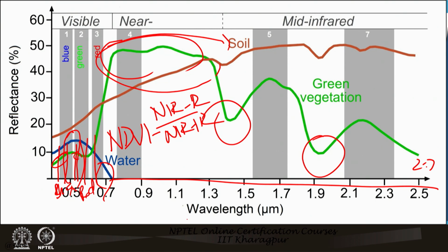So, if someone wants to just extract water, he or she would just take a near infrared band, and wherever it is 0 or at certain values. It may not be exactly 0, because there may be certain characteristics of that particular water body which may be emitting a certain amount of energy. There may be plants, etc. So, you look at the digital numbers, and with that range it can be easily separated as water and non-water. Okay, that is called thresholding.